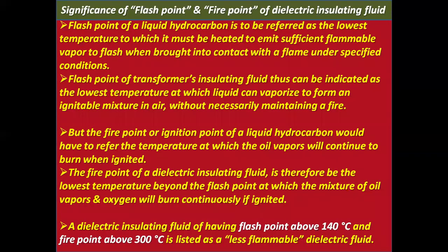Significance of flash point and fire point of dielectric insulating fluid. Flash point of a liquid hydrocarbon is the lowest temperature to which it must be heated to emit sufficient flammable vapor to flash when brought into contact with a flame under specified conditions.